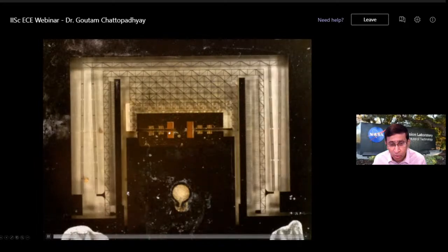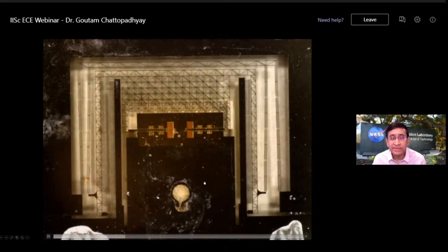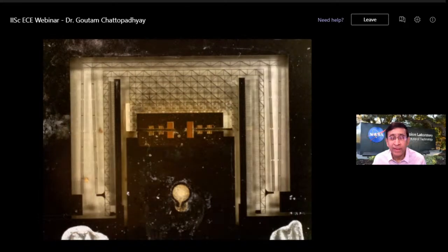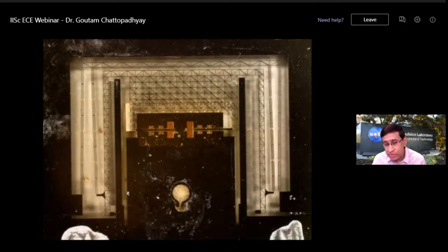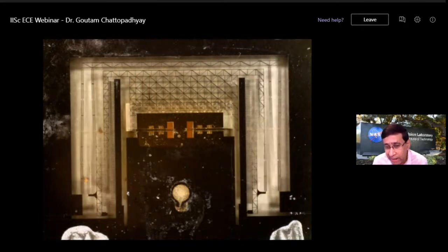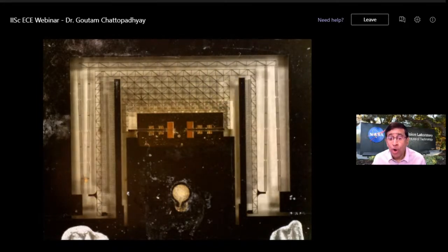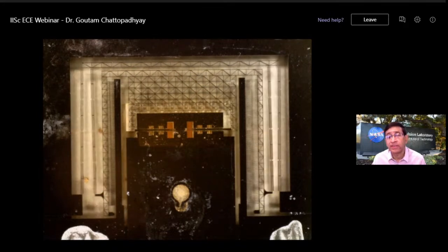You can keep an eye on the orange two blocks. That's where you can see that the septums are going in and out of the waveguide, and it's making a switch, and it's a very low loss switch at less than 1 dB of loss at 550 gigahertz.